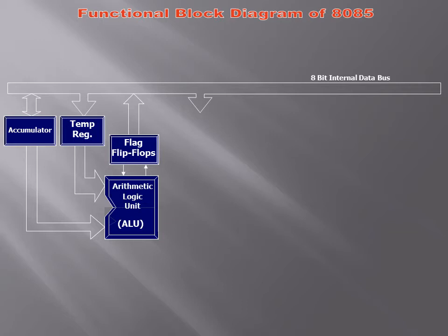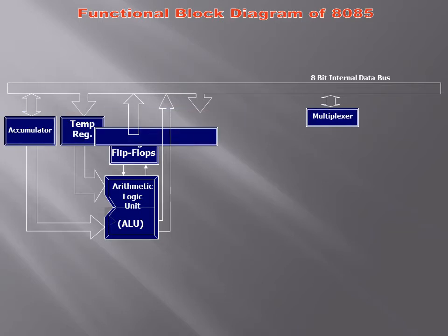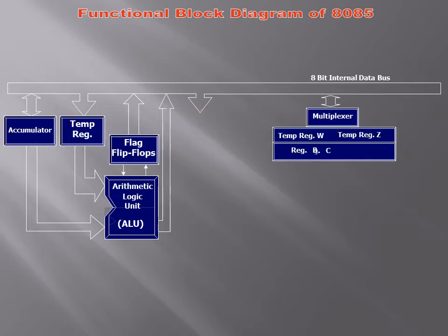So it needs a very little RAM inside, and that is provided as multiple registers. Those multiple registers include a pair of temporary registers WZ, which are not available to the user. These are used by the microprocessor internally for its own purposes.